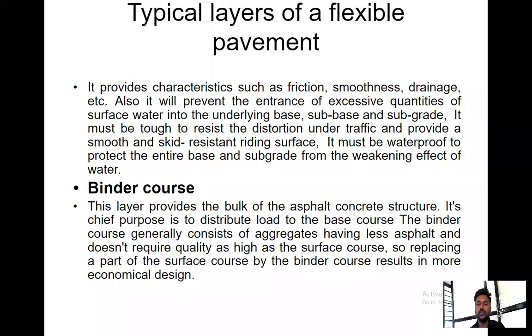It must be waterproof to protect the entire base and subgrade from the weakening effect of water. So these characteristics should be achieved by the surface. It should not let water enter into the base course. It should have proper skid resistance so that it gives riding comfort to whoever is driving on the road, and it must give waterproof protection to the entire layers below. These should be the characteristics of the surface layer.